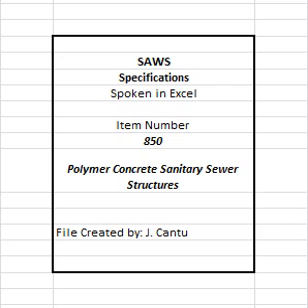CHDPE/grade rings are to be used in conjunction with a UV-stabilized internal polyethylene liner for the purpose of providing an infiltration/inflow (I/I) barrier. The approved I/I barrier is listed in SAWS APL. A note of clarification: a minimum of 2 and a maximum of 6 throat/grade rings may be used at each adjusted existing structure. F. Throat/grade rings are limited to a minimum of 2 and a maximum of 4 rings for new structure construction.